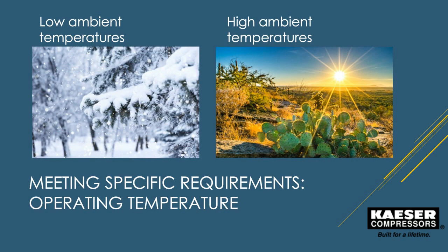In my opinion, one of the biggest misconceptions that engineers, customers, and such have is operating temperature. This is one of the most important factors. This needs to be determined up front in the design phase. We need to know, or you want to express, the lowest possible ambient condition and of course the highest ambient condition. Therefore, the package can be properly designed. The proper amount of insulation can be installed. Supplemental conditioning for air can be provided, or auxiliary heating can be increased.